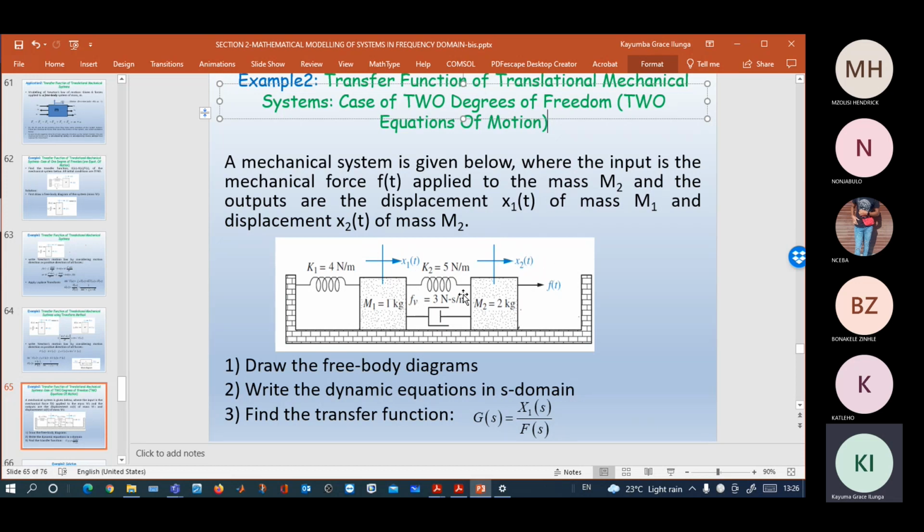What we need here is only the force coming from x1, but in the spring we cannot consider only one force. Because we are drawing the free body diagram with this mass, we must consider all the forces acting on the spring, but we subtract the force that is not concerned by this particular mass. Are we together?